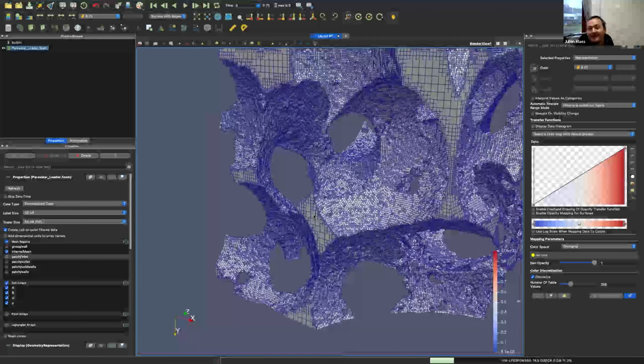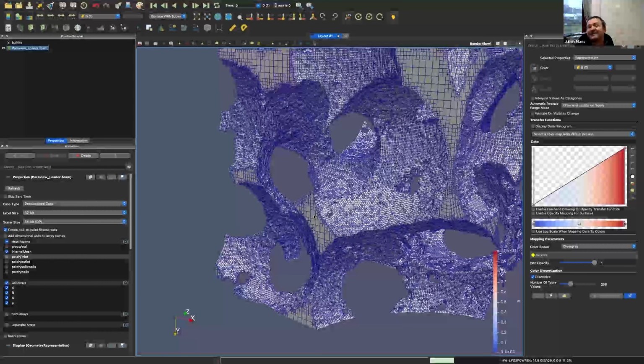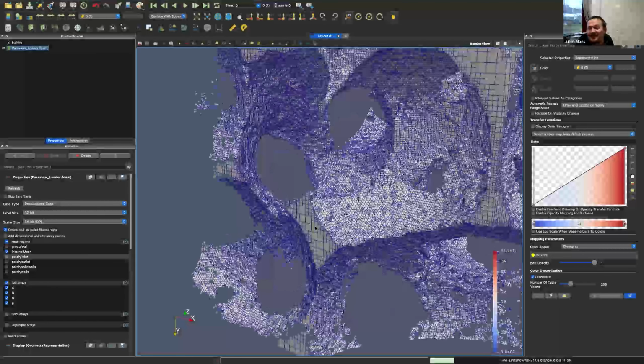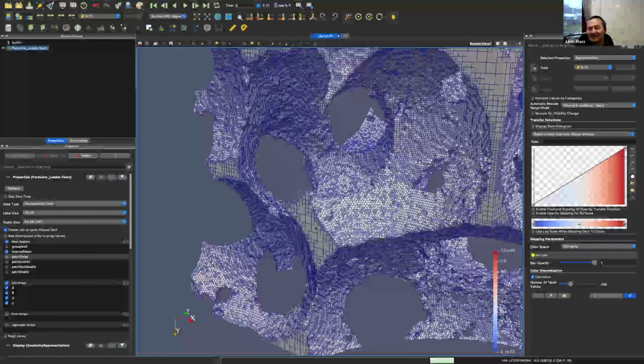Depending which side. Well, this is a transport of species, so we're not doing particles. I don't think it does matter. I think it's exactly the inverse. It's just an advection diffusion equation. If you switch, the streamlines are the same, they just reverse, and it's exactly the same transport.